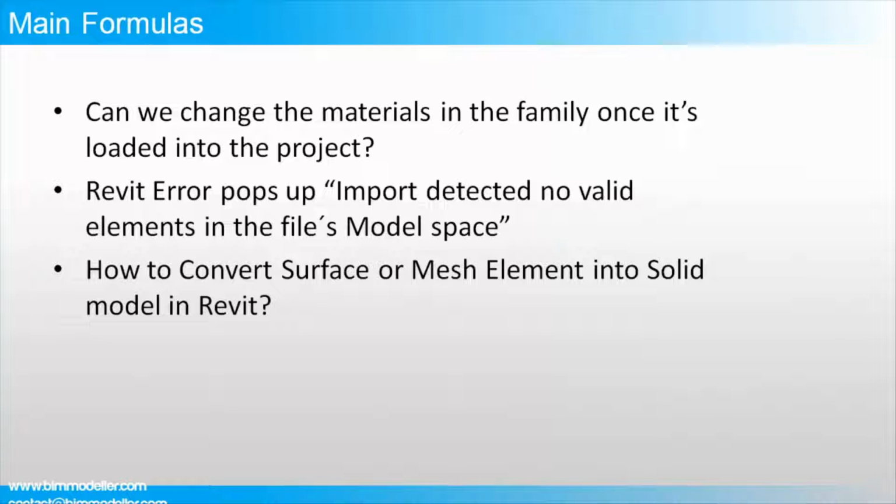These are the basic things. Otherwise, you can use Inventor or any other software which helps us convert the mesh or surface into a solid element. You can give the thickness in that software and convert those back to Revit elements. Since Inventor is an Autodesk product, it can also export a Revit family. You can try Inventor and then export the same to Revit as a Revit family. It is possible.